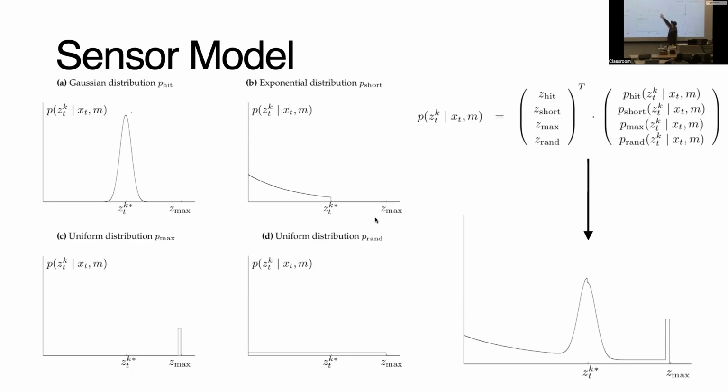And then we have this distribution moving up to the distance we measure. And this is measuring basically that the laser hit short. And so the probability that we get a return that's actually before the actual obstacle is going to be something falling off exponentially from our minimum. Now, what would cause this?